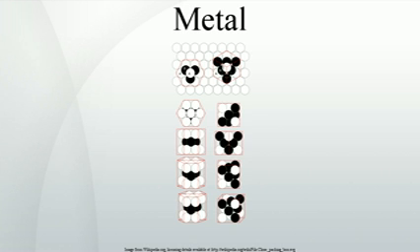When a metal ore is an ionic compound of that metal and a non-metal, the ore must usually be smelted, heated with a reducing agent, to extract the pure metal. Many common metals, such as iron, are smelted using carbon as a reducing agent. Some metals, such as aluminium and sodium, have no commercially practical reducing agent, and are extracted using electrolysis instead. Sulfide ores are not reduced directly to the metal but are roasted in air to convert them to oxides.